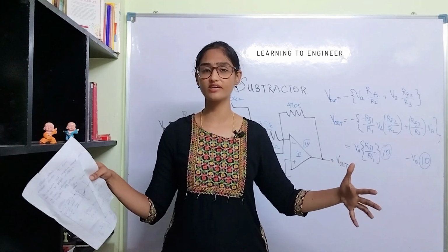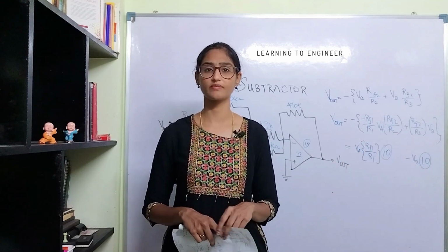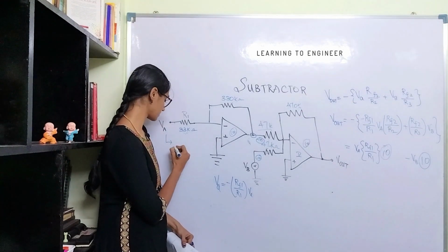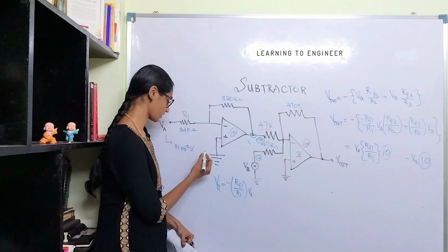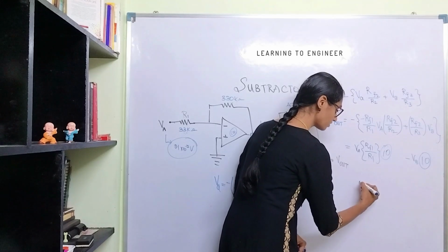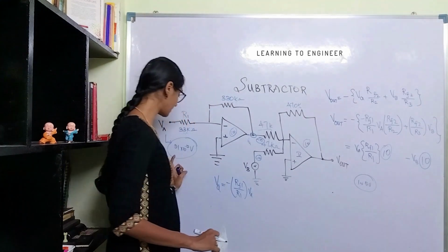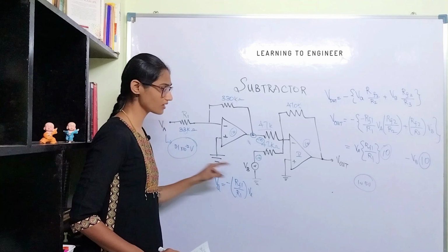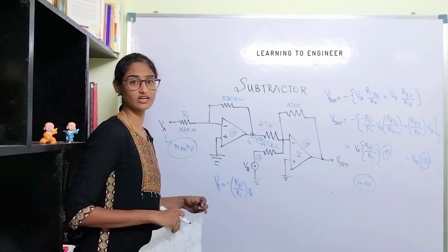One single amplifier we cannot use, let us say, to multiply by 10 power 12. Okay, because if the sensor's input at one stage is, let us say for example, 0.1 into 10 to the power minus 12 volt, for that to be measured by a readout, you need this output to be 1 to 5 volt at least. Let us say for example, how will you do a multiplication? You have to multiply it by at least 10 power 13 so that you can get 1 volt. Okay, so 10 power 13 should be the gain of that amplifier.